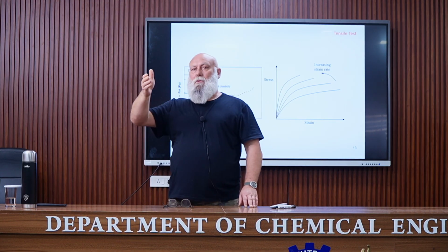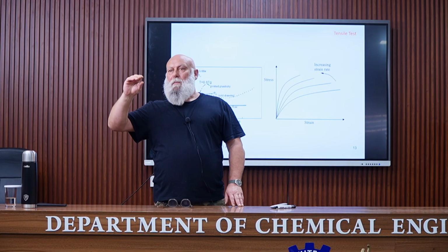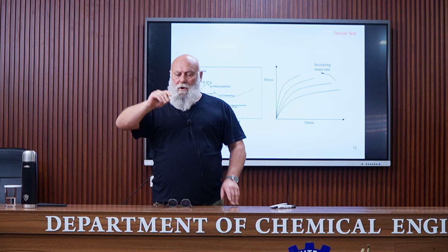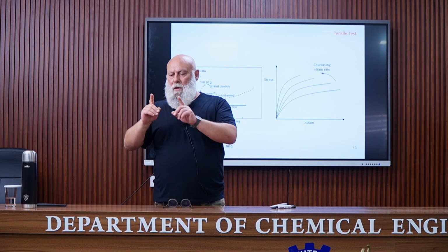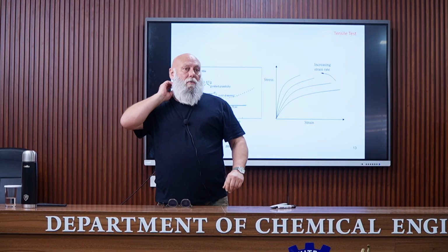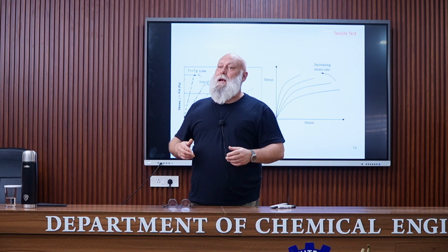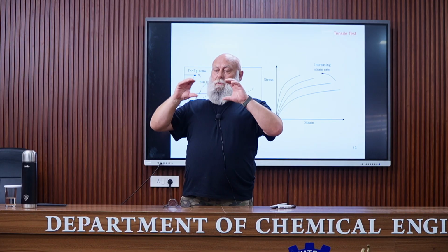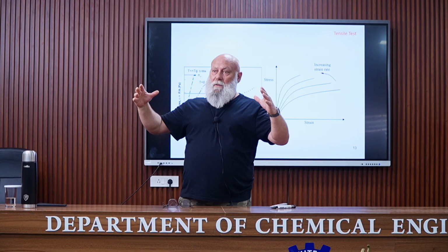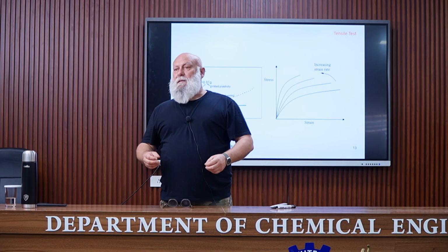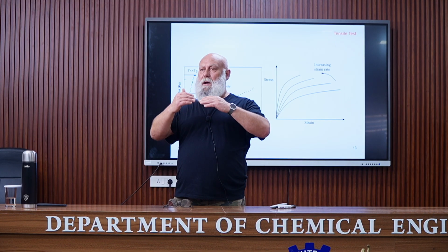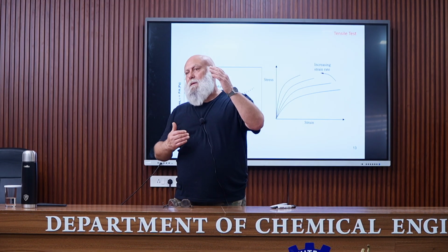In fact, the crystalline domains can be viewed at different levels. The level of a single macromolecule, and the level of a collection of macromolecules that form what is called the crystalline lattice, or the crystalline lamella, or the spherulite. And in fact, during a tensile test, the crystalline lamella will progressively break.